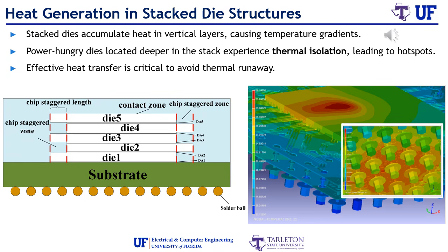Engineers respond by reordering die placement so high power dies are closer to cooling surfaces when possible, splitting a large die into several smaller ones to spread power, using power aware techniques like clock gating so not all high power blocks peak at once. Combined with better materials and vertical heat paths, these strategies help keep temperatures within safe limits and protect device reliability.